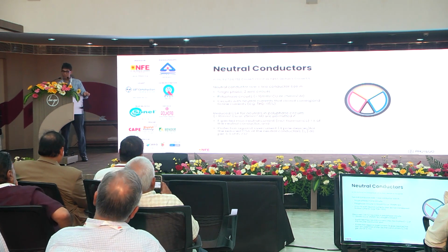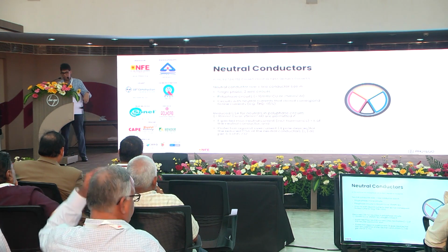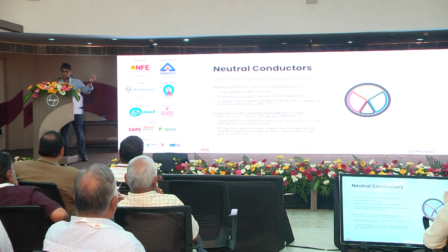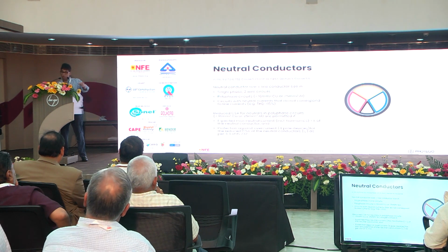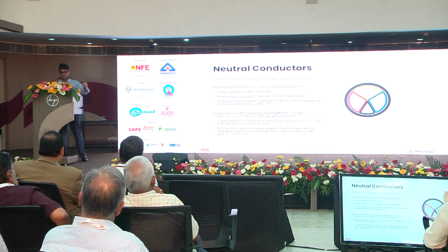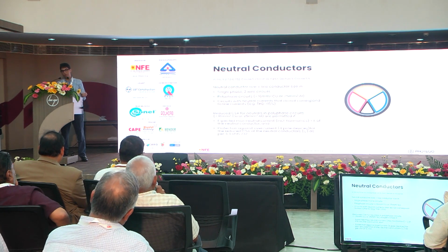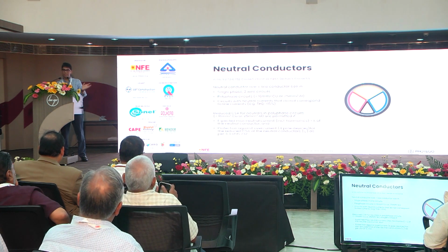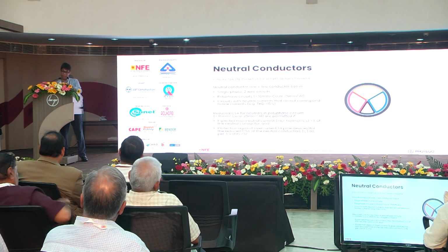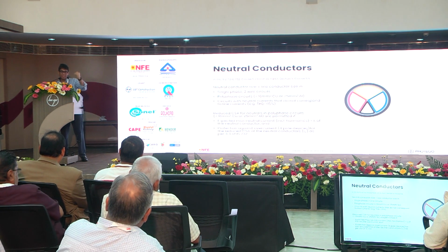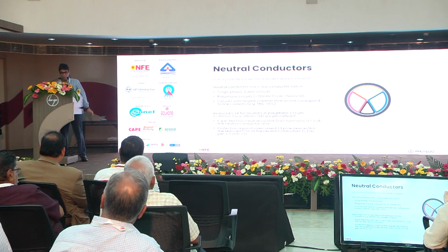If it is a polyphase circuit where the cores are not very big, say 16 square mm copper or 25 square mm aluminum, if they are lower than this, then there is no scope of this as well. And if there are triple harmonics, which to be honest are most loads, especially triple harmonics greater than 15%, then you may not. Where can you do this? If the neutral current including harmonics is lesser than the current carrying capacity of the neutral conductor. But bear in mind, if this is the case, you need to derate for 4 loaded cores. As per 60287, the rating factor is 0.86. So only 86% of the current carrying capacity can be used.